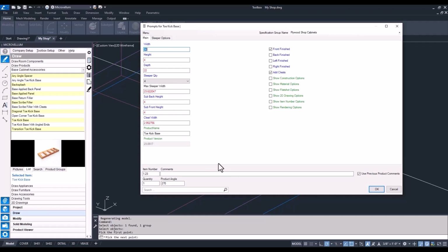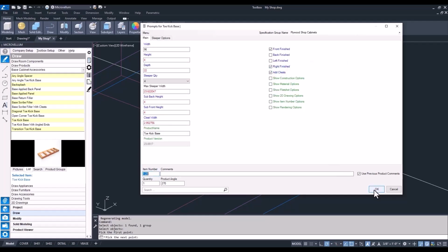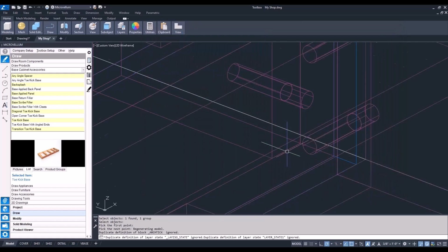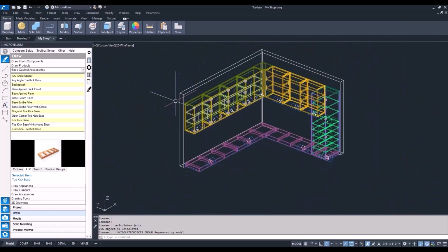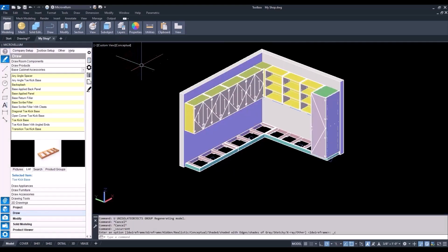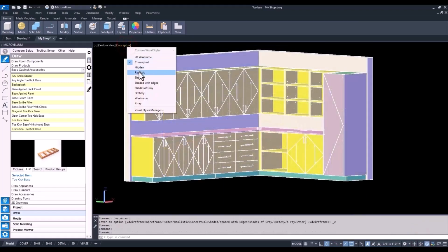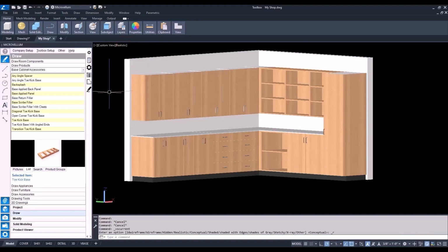But I'm not worried about that because we have to turn on our right finished end anyway. With the right finished end turned on, the overall length of this toe kick with its finished end is going to be 96 inches. Once we take the material thickness of our finished end, it's going to make that actual toe kick part 95 1/4. So that should fit within our material limit. So we should be good. There we have our solid kick skin on the front, finished end on the right. Unhide those objects.